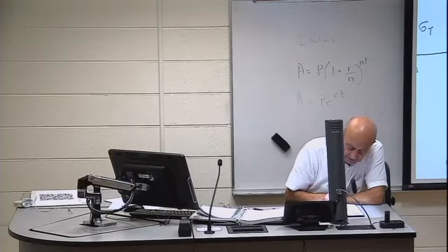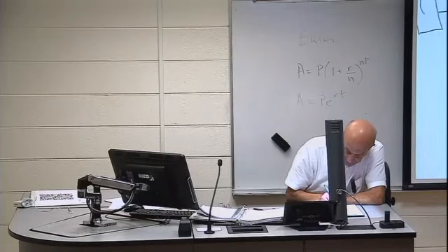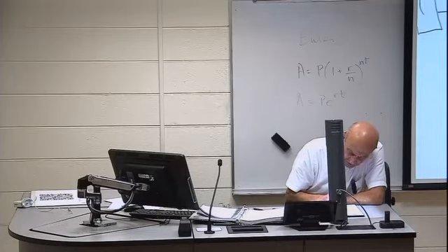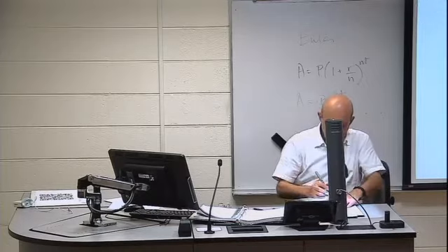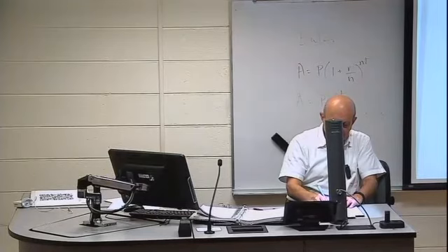So sigma allowable equals sigma yield divided by factor of safety. Okay? So this factor of safety is bigger than 1. And this is usually also called RFS, required factor of safety.